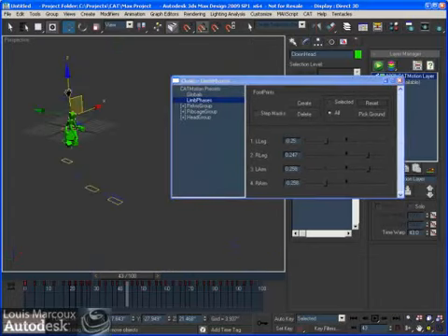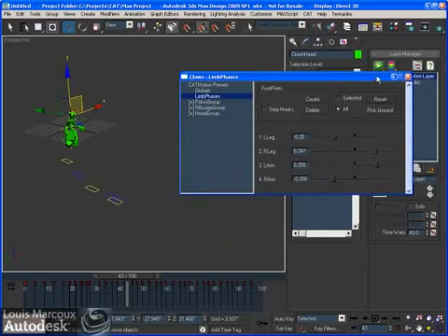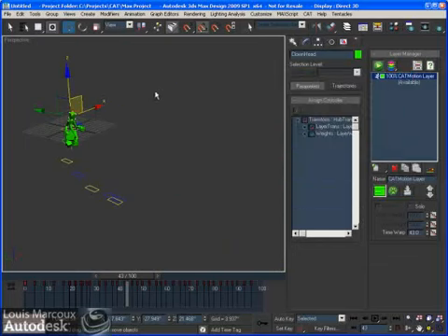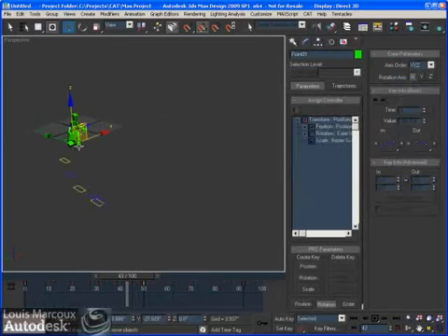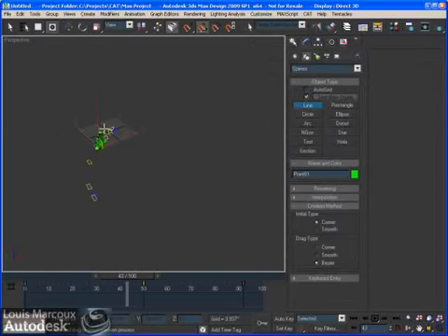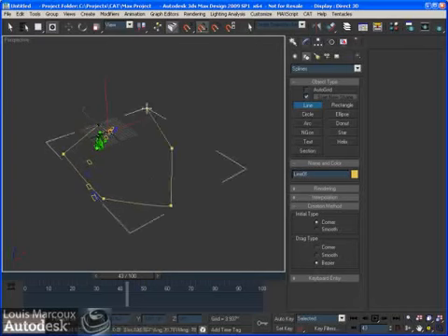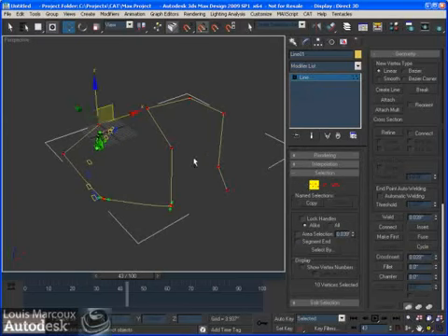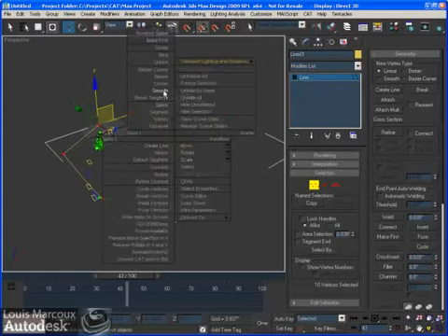So what I can do as well, and it's actually a Max feature, not a CAT feature, but it's going to be interpolated by CAT. If I take this path node, I can create a line on the ground here. Let's say I'm doing something like that. Not too long, but something like that. I'm going to press Ctrl+A, and I'm going to make that all smooth.